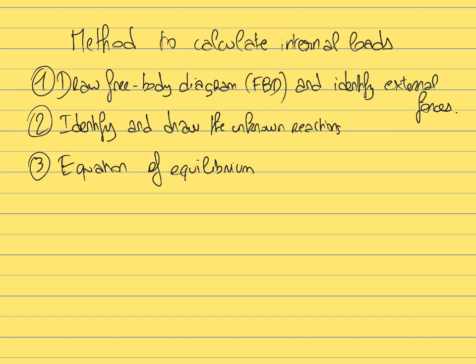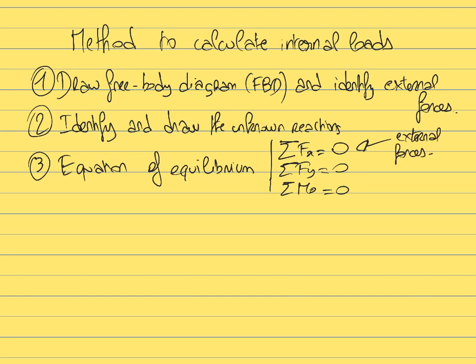So in this case, when I say condition of equilibrium, that's what you saw in statics. The sum of the external forces along x equals 0, the sum of the external forces along y equals 0, and the sum of the external moment about a given point, O for example, is equal to 0. So this is only about the external forces, right? So you need to isolate a given system and figure out what the external forces are.